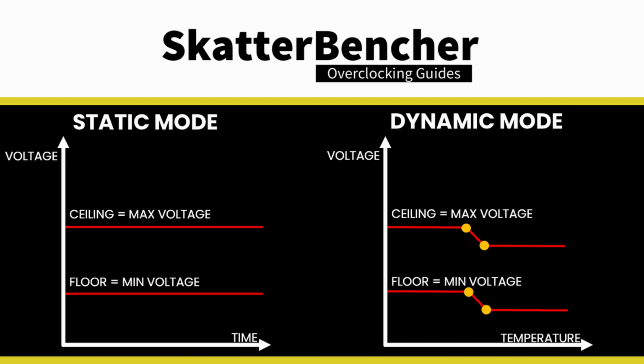In dynamic mode, we make our own voltage frequency curve, though we don't use frequency as a parameter. Instead, we configure the ceiling and floor voltage as the function of 4 points defined by voltage and temperature. So I guess it's more like a voltage temperature curve. It gets a little bit complicated in the BIOS, but here's what it boils down to.